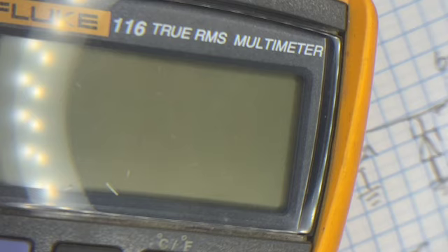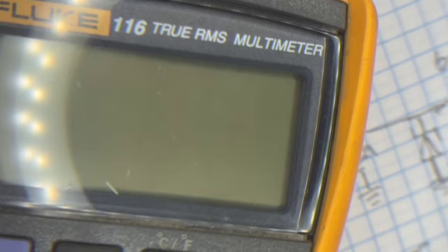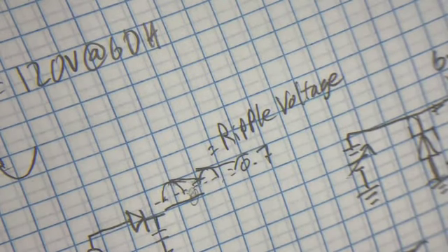And as you drop that resistance lower and lower, the voltage that you read also drops lower and lower until you get to a point where you don't see any voltage difference between the two terminals. That is essentially when you've got such a low impedance that it's essentially a short. So why is there that drop in voltage from the open source compared to the source with a load?